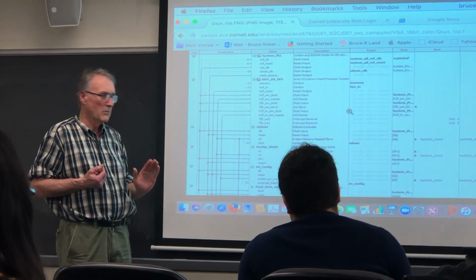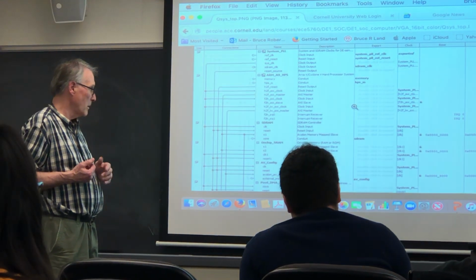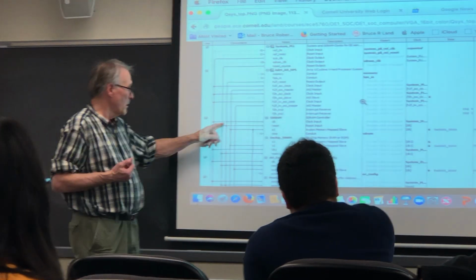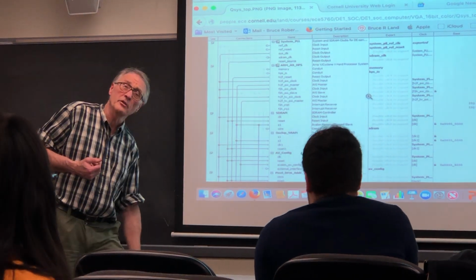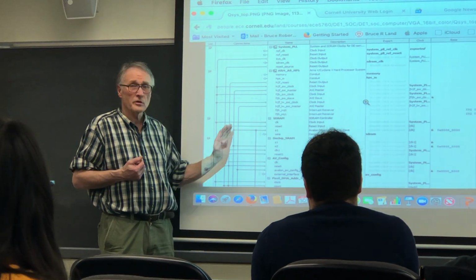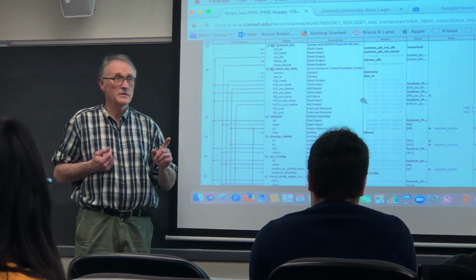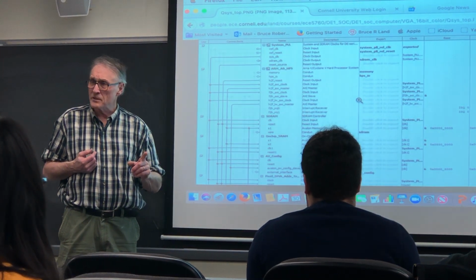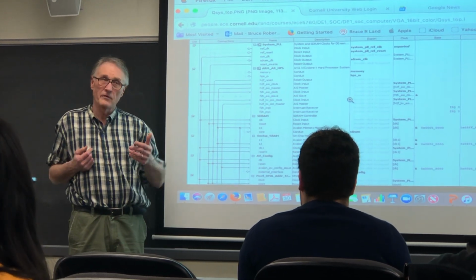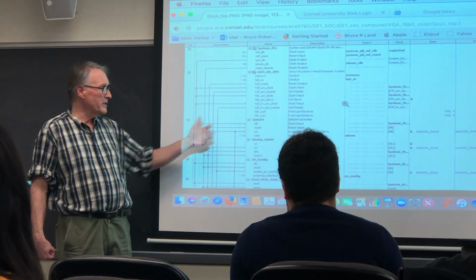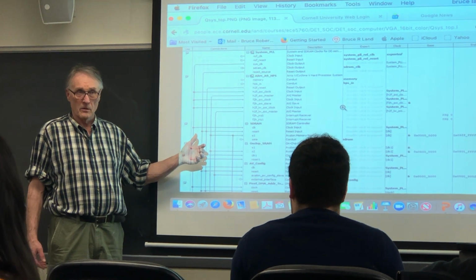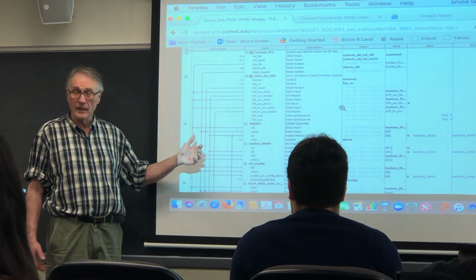So what's going on where it looks like you've wired your H2F heavyweight AXI master to S1 of the SDRAM, but that also is wired to a different plane? That's perfectly fine. You can have two masters wired to a single slave, and the bus structure resolves the conflicts. So it is a multi-master, multi-slave bus. The bus itself, the code you never see, the Verilog you never see, generates contention control and resolves contention. So you can pretty much hook these things up the way you like and it'll work.